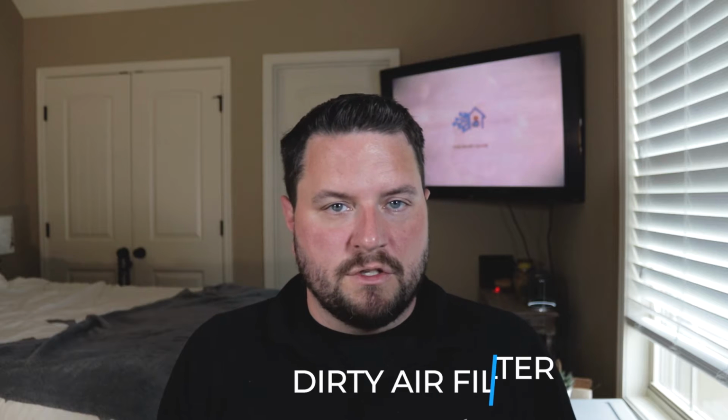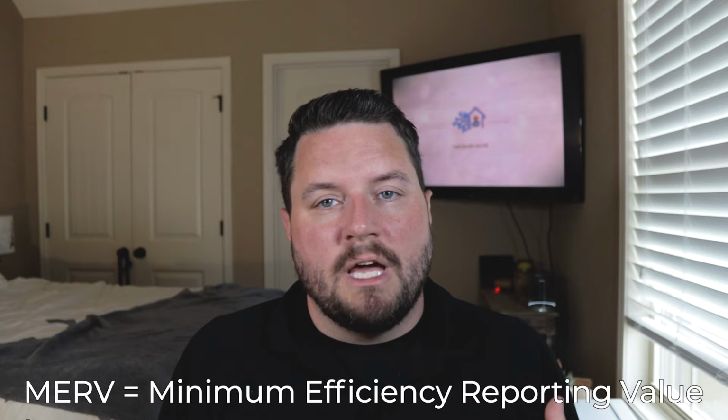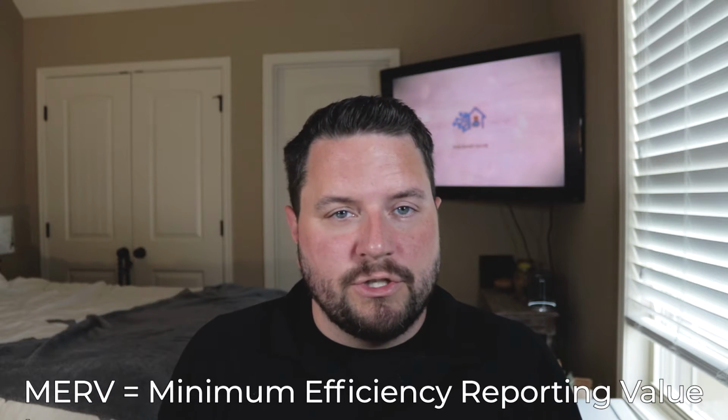The next most common thing that you're going to run into is that your air filter is clogged. So if you have a thick air filter, like a high MERV air filter, and it gets clogged up with dust and allergens, it's going to reduce the amount of air that can flow over your evaporator coils and then cause the unit to freeze up and stop functioning. It needs all those little tiny fins to be exposed to allow the heat to be exchanged out of the air and into the Freon.